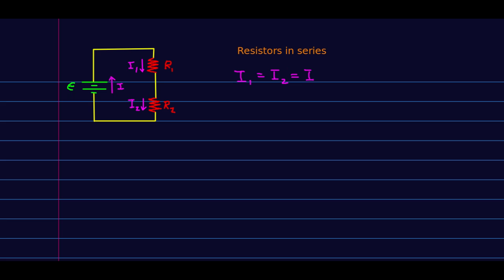So think about how Kirchhoff's loop law will play out. If we think of walking around this loop, we can now write down the voltages. We walk up a voltage epsilon as we step through the battery. As we step through the resistor, the voltage drops. We're going with the current, and these charges are losing electrical potential energy as they go through the resistor.